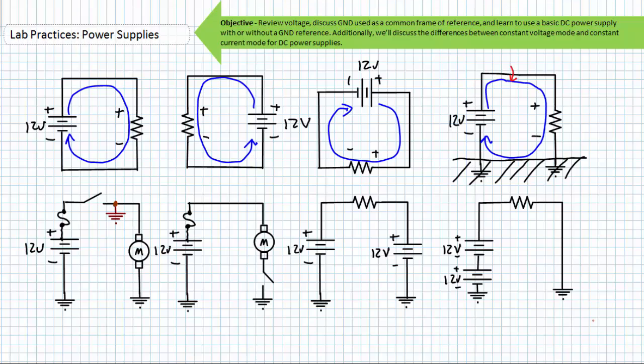What would happen if an accidental ground connection in the form of an errant wire or connection with a frame occurred on one side of the switch? If the switch was closed, what is the resistance for the high side switching arrangement? In this case, it would be 0 ohms of resistance, because all three of those ground symbols really are kind of a single point.